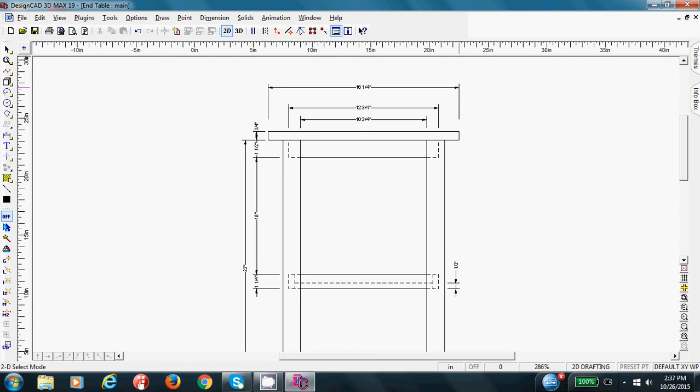That does not look even for some reason. I wonder why. Oh, so we have some issues here. I am dimensioning from the wrong place. So this is right, I'm dimensioning from here to here. However, my gap should be 0.3, and it's not 3.75 anymore because I don't have to account for this. If I didn't want to change anything, if I click from this point to this point, it's going to work just fine. So let's do that so we don't have to change any numbers at this point.